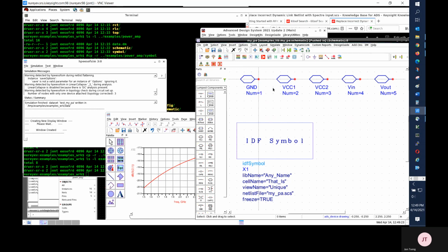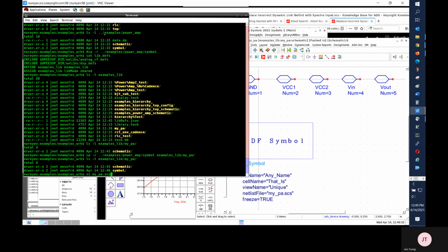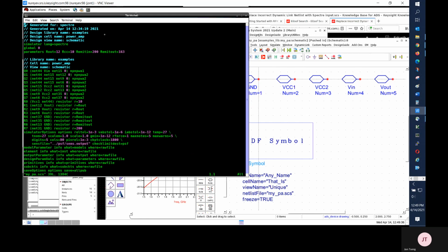The reason for the wrong result is that port names in the schematic should match the connecting nodes in the Cadence netlist, but it is all capital letters VCC1 and VCC2 in the schematic, while in the netlist only the first letter is in uppercase. You need to watch for this type of mismatch.